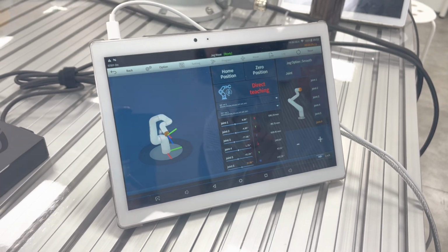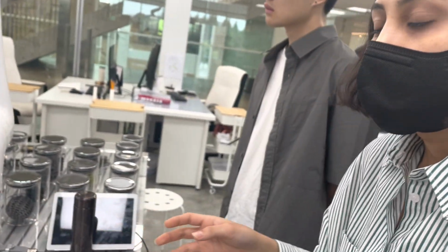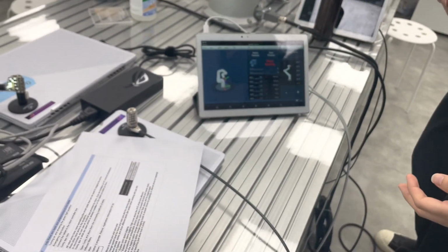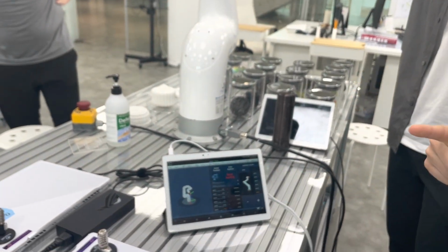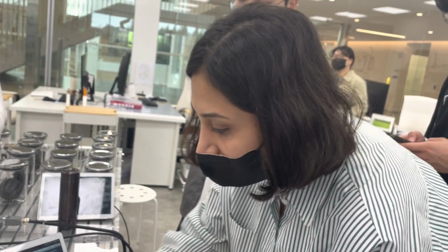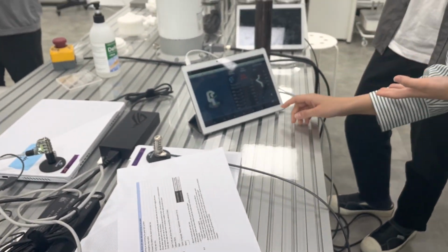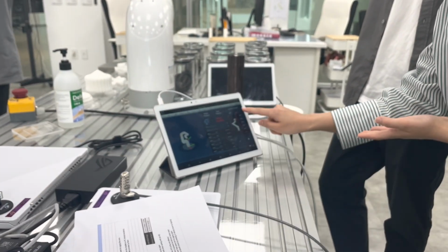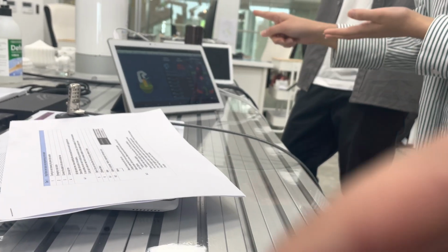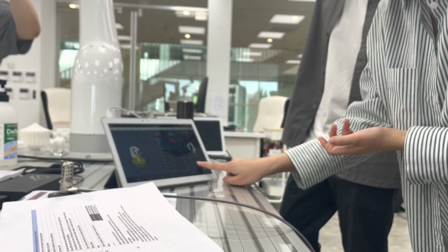And something that you should know is that for each robot we have some limitations. For example, the first joint, I guess from joint 0 to 5, can be from minus 175 to plus 175, and the last one can be like minus plus 250. But when we are working in task space, I guess it's better to first go to home position.